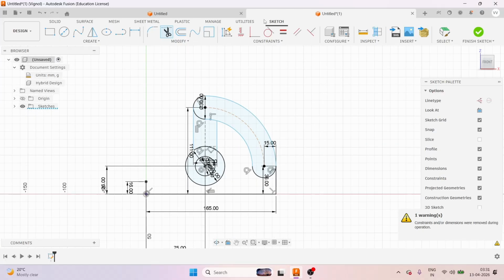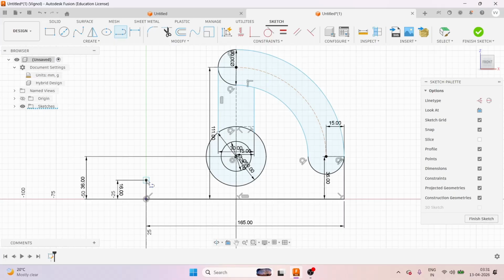So we're going to toolbar and select line tool, and then we can select this end point and then move it to the right until it finds this cycle in this case, and then we can click it once and you'll see that it has already closed in this case.